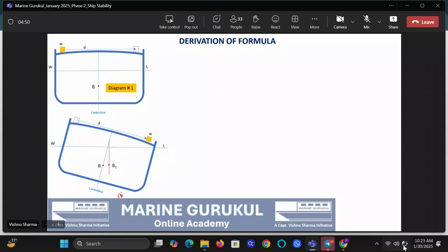You see, it goes here, this is list. Now, this is the distance in the equilibrium condition through which the weight W has been shifted. And this angle is 90. This angle is theta equal to list. Therefore, from this triangle that has come up now, what is the horizontal distance between the two locations of W from the lower diagram? It will be d cos theta. Am I right, class?